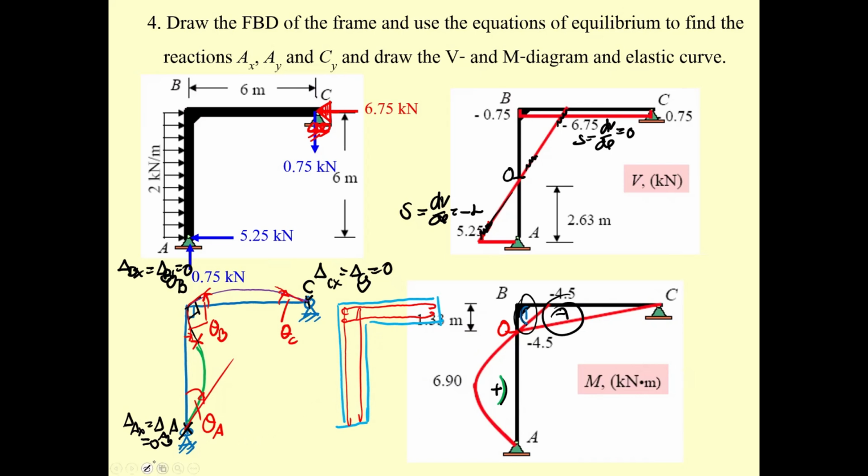But based on the bending moment diagram, such as this one, you have to put extra steel over here.